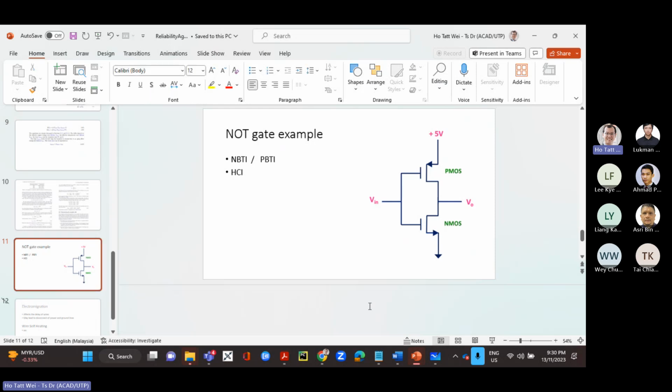So you know that resistance is dV over dI, right? This is resistance. So if you have a graph of I versus V, the slope of this graph is 1 over R. So then you can actually estimate what the R of this is.